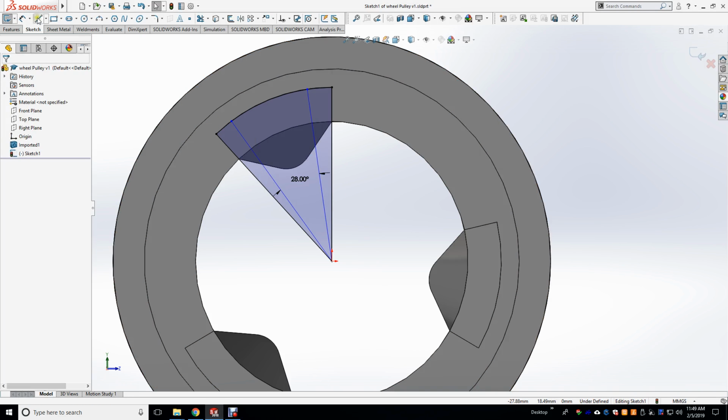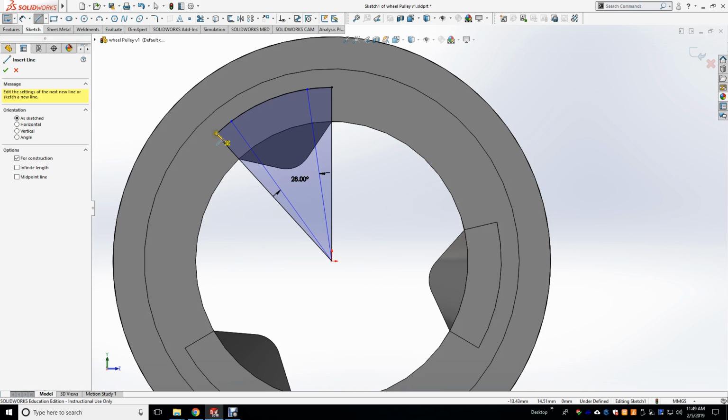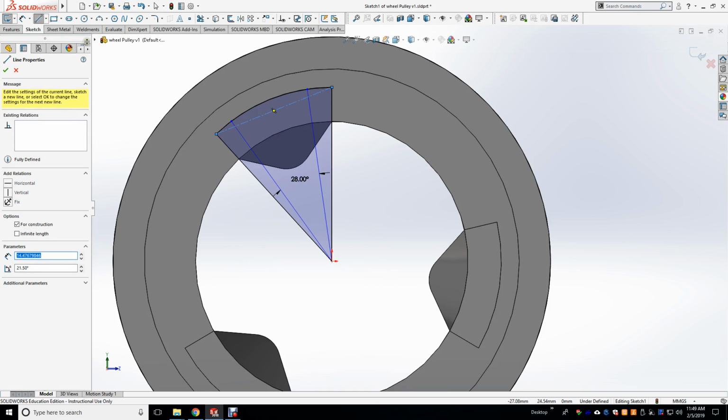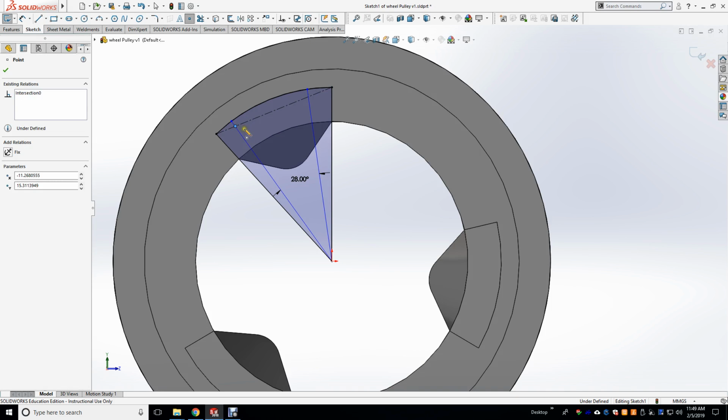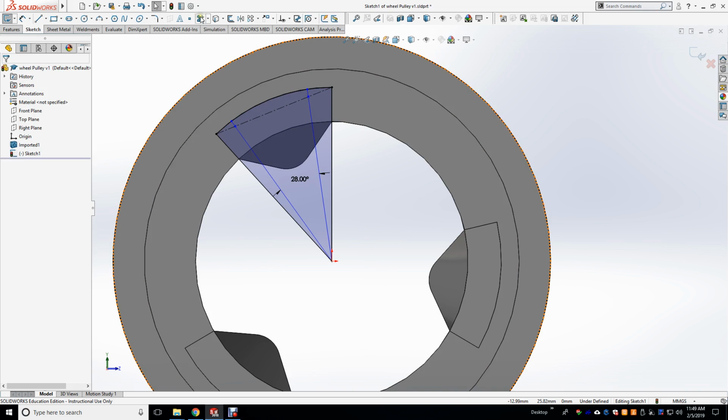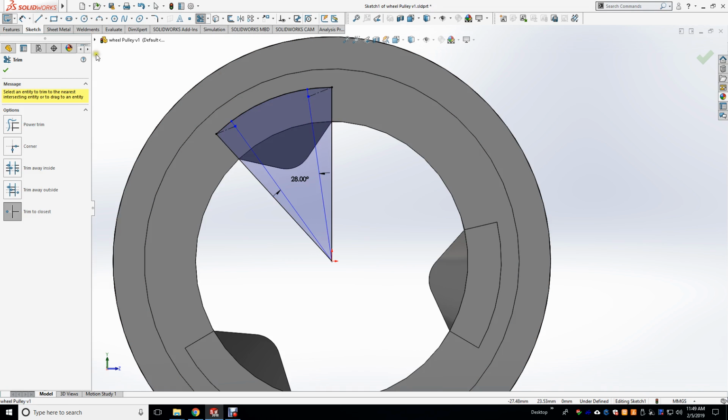Now we're missing a constraint that makes the left and the right sides trimmed equally. This is important. One way to solve that is to use a center line from corner to corner. Then grab a point. That point will be constrained to the intersection of these 2 lines. Based on the small icon behind the pencil icon, it shows that this is constrained to the intersection. Okay? Now you have 3 line segments. We're going to trim the middle segment. Now you have 2 line segments, and we're going to use not the smart dimension.